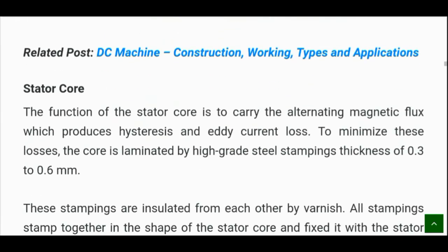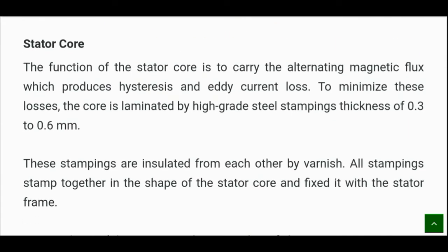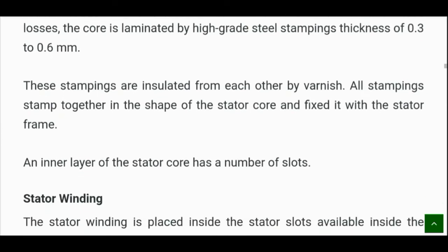Now the term stator core. What is the stator core? The function of the stator core is to carry the alternating magnetic flux, which produces hysteresis and eddy current loss. To minimize these losses, the core is laminated with high-grade steel stampings of thickness 0.3 to 0.6 mm.